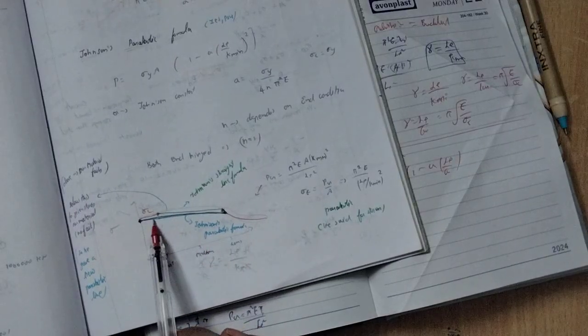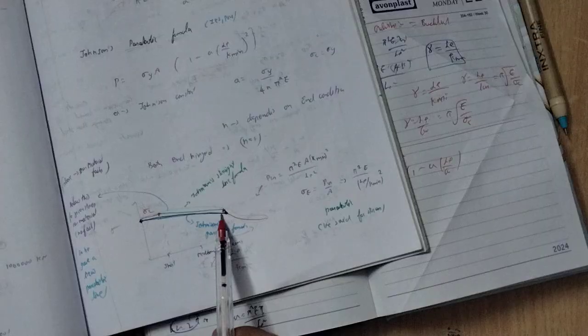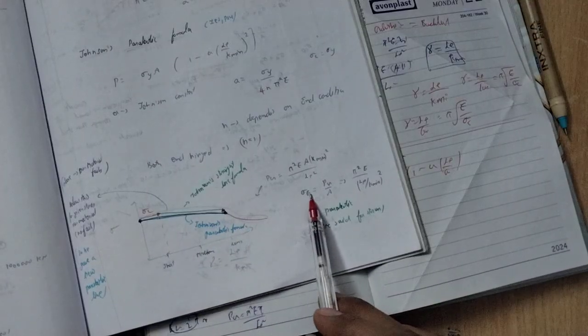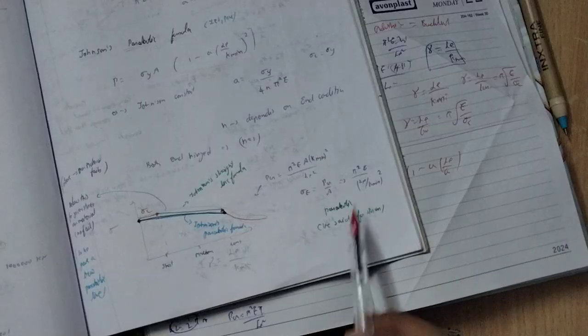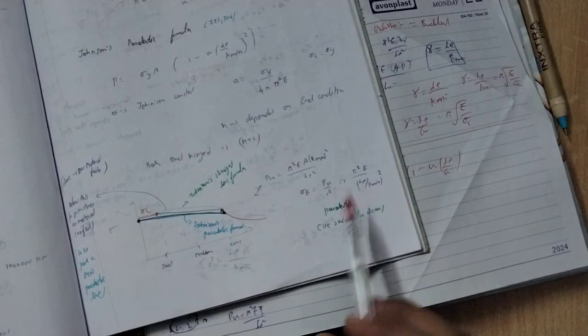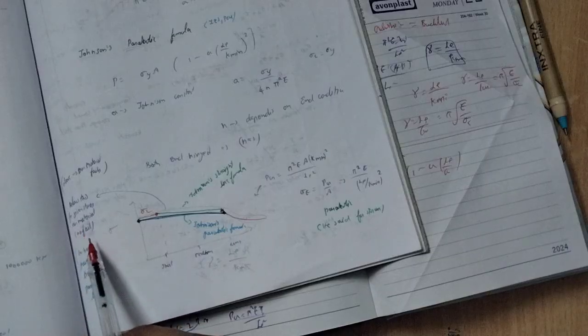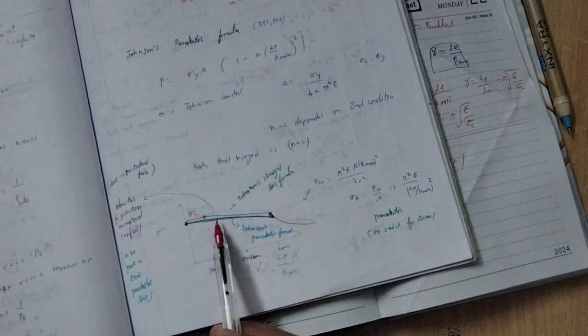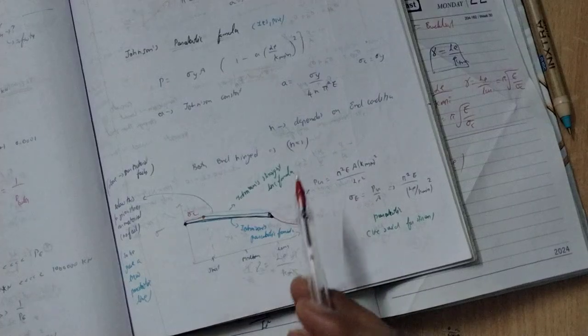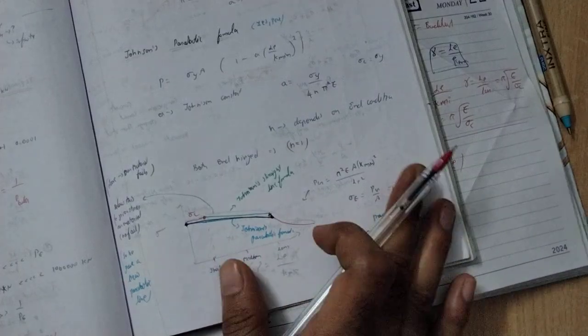and you can see Johnson's parabolic formula lies a little bit downward. Okay, and you can see here that the crushing stress tends to be in parabolic form. For the stresses it will be parabolic. Below this given stress no failure occurs. It means, you can see this one line, below this mostly no failure occurs, but above it definitely failure occurs. Okay, I think you can understand.